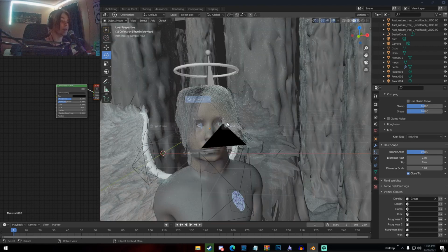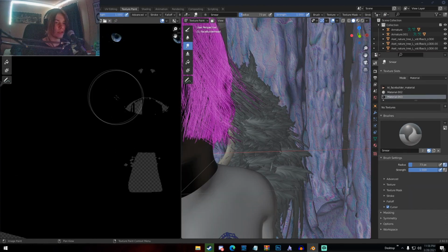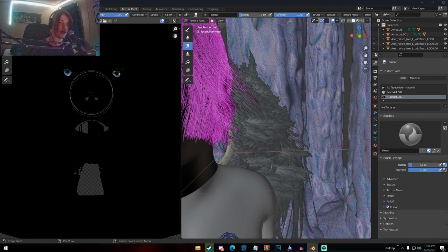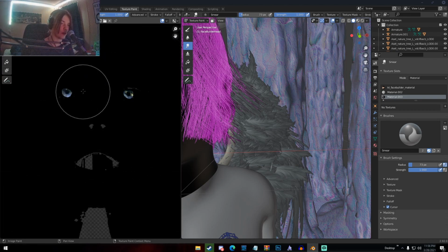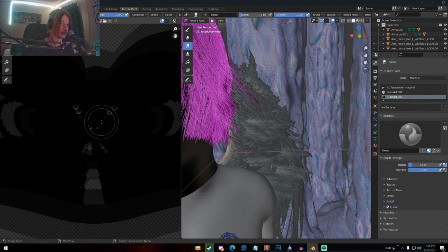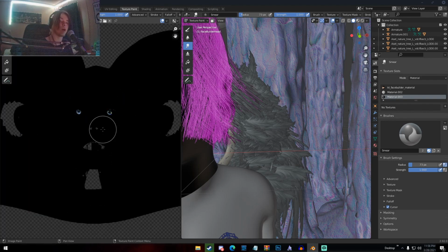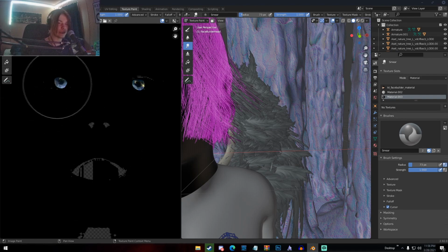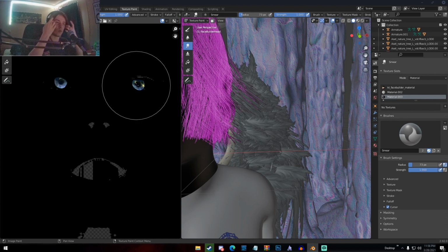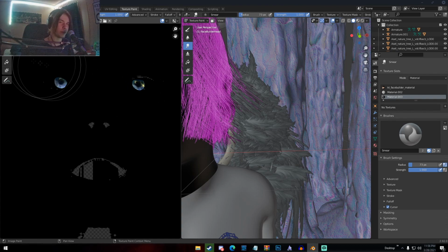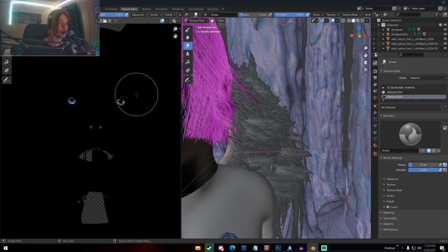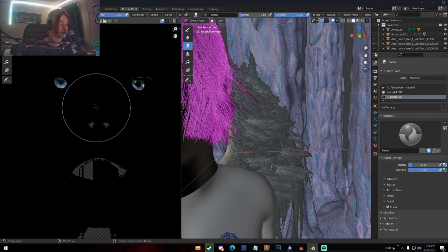Basically, that is from Emission Maps. This is my Emission Map. Okay, so you can make one of these. It's pretty easy. You can make these in different ways. So it looks kind of creepy, I know. But basically, all you need to know is everything is black except for the eyes, which have color data, and they're pretty bright. You're going to want whatever you're trying to emit pretty bright. You don't have to make it extremely bright, but don't make it really dark. It works better if it's bright.